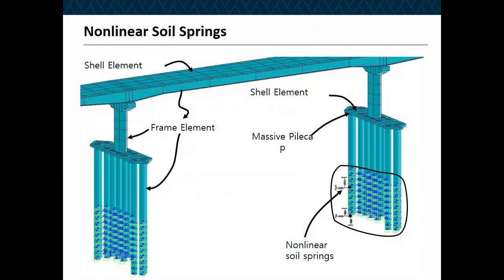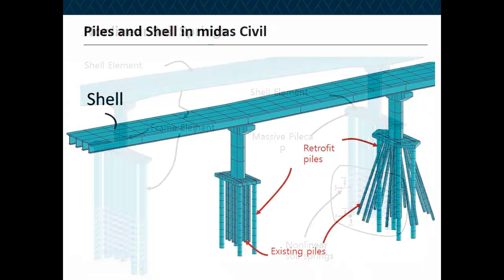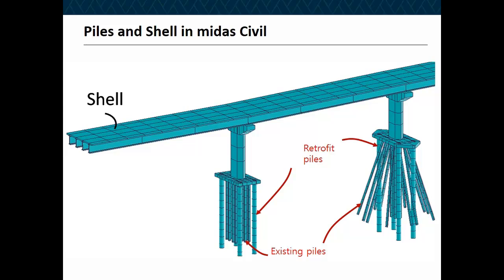Again, nonlinear springs, closer shot of the piles. These are nonlinear springs attached in Midas. One thing about the new version of the Midas, I don't know for those of you who are using Midas if you have the latest version or not, but you can basically develop your nonlinear springs outside Midas and copy paste them in Midas. It has a new option now that you can develop your nonlinear springs, tension and compression, and easily copy paste them in Midas and then attach at every node. You can attach those springs very easily. Again, closer shot of existing pile versus a retrofit piles here.